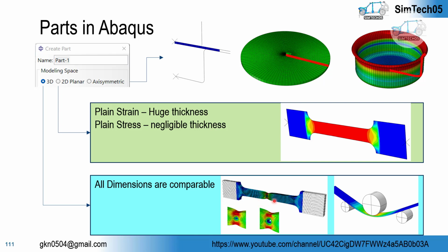So for that damage analysis, we model our component in 3 dimensions and perform the analysis by holding from one end and applying load on the other end. Similarly, here you have one plate. On that plate, you want to apply some bending load.